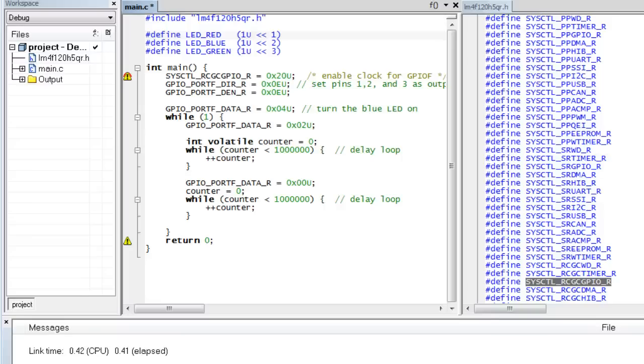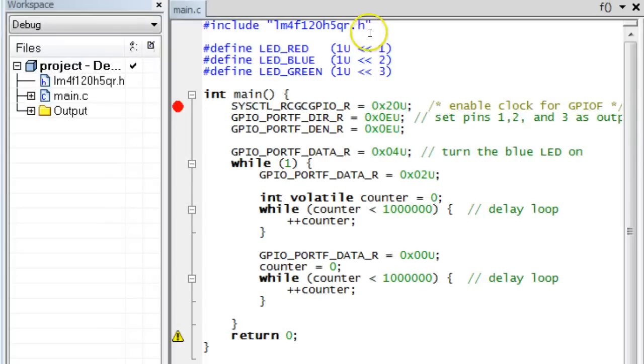This way of defining bit constants has saved me a lot of time counting bits and prevented a lot of stupid bugs in my programs, so I highly recommend it. After defining the macros for the LED colors, you can replace the cryptic hex numbers, which greatly improves the readability of your code. In fact, your code becomes self-explanatory and the comment becomes redundant.